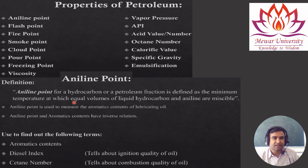So what is aniline point? You can see the first we will come to know about the aniline point. The definition of aniline point is written here. Aniline point for a hydrocarbon or petroleum fraction is defined as the minimum temperature at which equal volume of the liquid hydrocarbon and aniline are miscible. So that means equal volume we will take of aniline and equal volume we will take of hydrocarbon, and we will mix it and we will note down the temperature at which they are miscible.